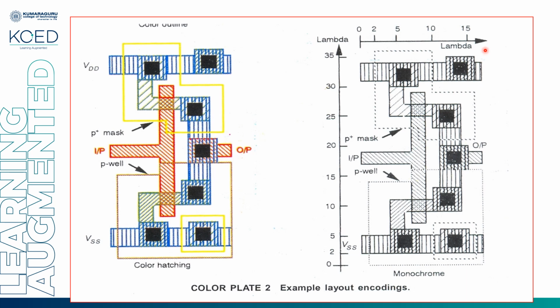minimum width and spacing nearby each and every layer, each and every block. So again here you have a P substrate contact. I have not done this in the previous slide, so here I must do it for VSS. Why? I told you inside a P well we fabricate an NMOS.